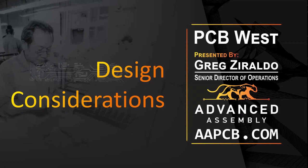is a laminate that actually uses aramid fibers as a base construction rather than woven glass. So this is going to support weight reduction and is very strong. However, it will absorb moisture very quickly and will require extensive pre-baking and vacuuming prior to post-lamination. So basically with this material, it's almost like particle board if you're looking at a wood reference. So instead of actual grains of wood, it's essentially fibers, almost looks like cardboard that's pressed together and bonded with resin. And what this material does is that it's incredibly strong. It's very, very lightweight, but it absorbs moisture like a sponge.